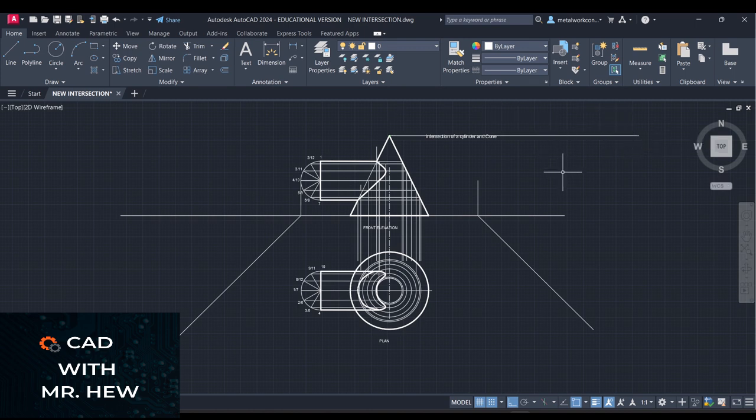We're gonna do the same thing in the plan so that we have established what we have done. We have drawn the height that we would need in the end elevation, okay? All right, now we're gonna draw another line from here as it was a little bit short. So you would have used a T-square to extend the line.